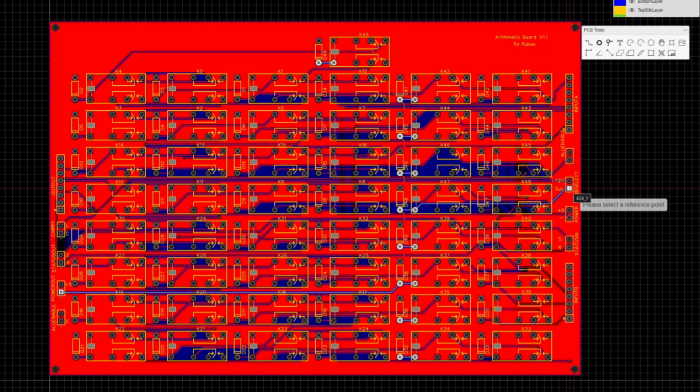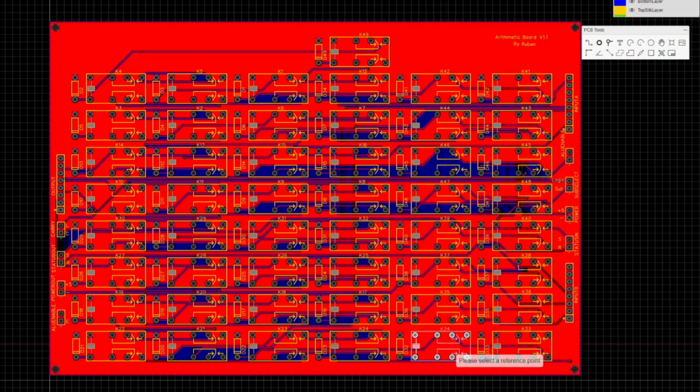So when this is activated, these relays will basically compute the 2's complement of input B, and then all it does is add the 2's complement to A to subtract it. And here are your adders. It's a ripple carry adder, so nothing too fancy. And here we have the 1's complement, and then to make 2's complement you just turn the carry bit on into the adder, which basically adds 1. And that's how this system works.